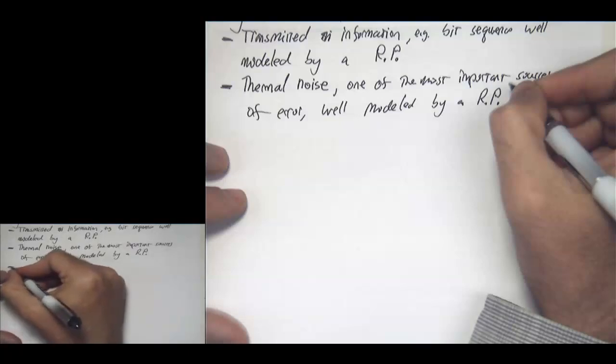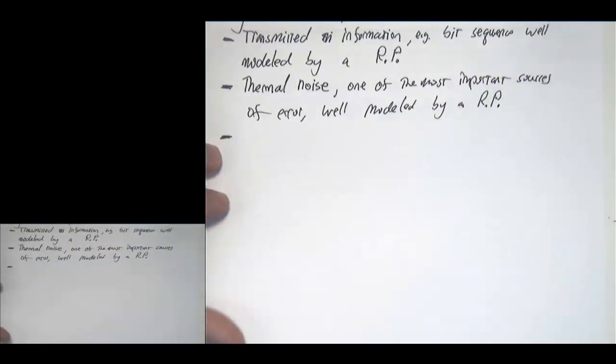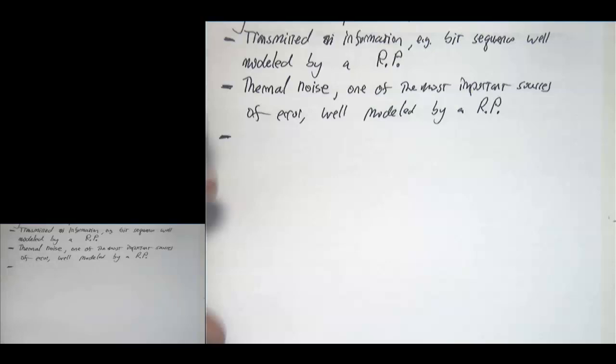And then further, the propagation environment. If you think about this from an electromagnetic perspective, we have a transmitter on this side and a receiver over here. We could model everything in here, all of us, based on our material properties. We could do a ray tracing simulation and compute the field strength all over this room, right? It's deterministic. The thing is that whenever someone moves or shifts around, or we don't know exactly the material composition of everybody. I'd have to know what you ate for breakfast and all of that. It doesn't make any sense.